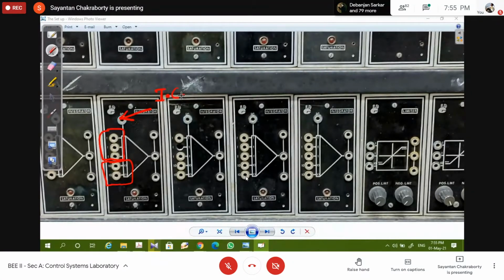What we are missing in this particular realization of the circuit diagram is that this integrator has 3 to 5 inputs, with 3 inputs having multiplier 1 and the rest having multiplier 10. So you can have integration as well as summation; you can integrate 2-3 signals and sum simultaneously.